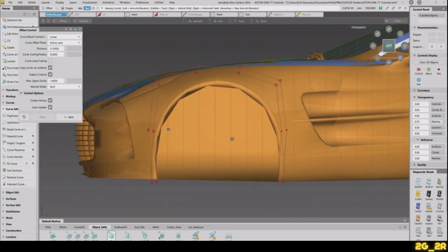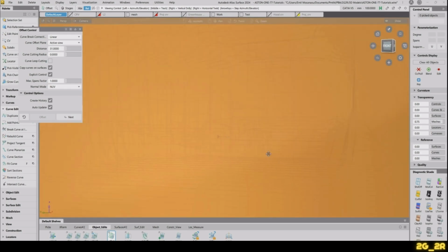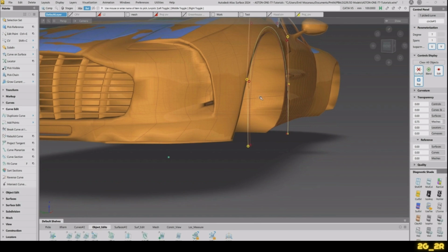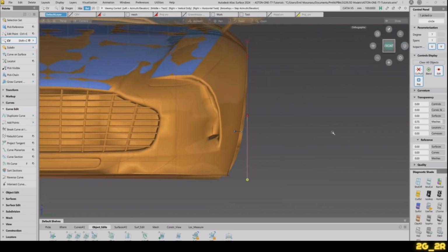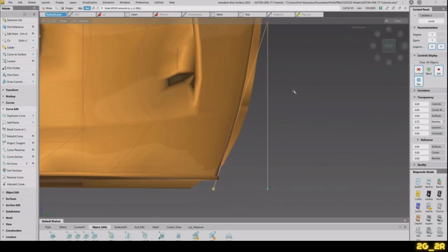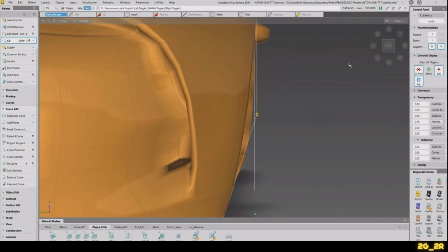So it's pretty good. Now in the front view, we will start tuning the line to fit the scan. So I'll turn the CVs on the offset, so I don't accidentally move them, thus destroying the history, because I like working with construction history. So now I'll just pull the CV in here. We want to achieve this to resemble as much as we can the lines that we see in the front view. So that will be that here. I will want to go outward.